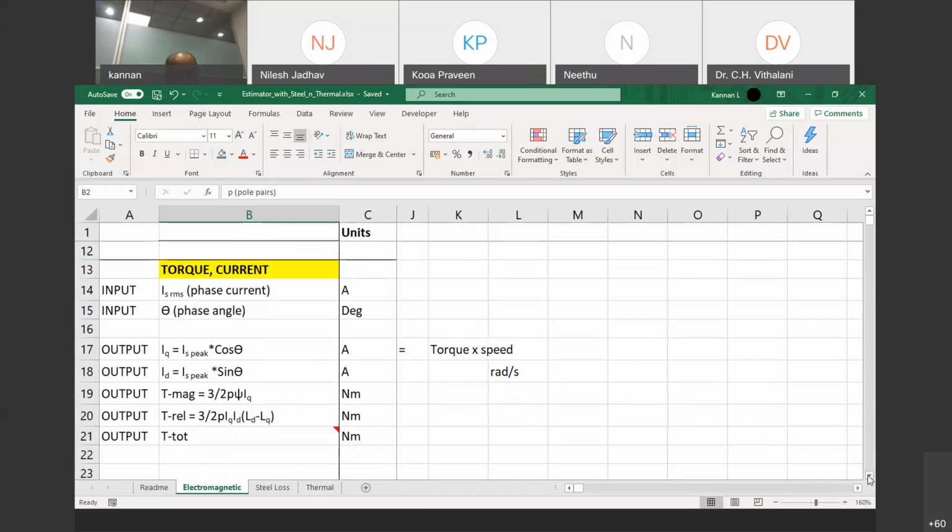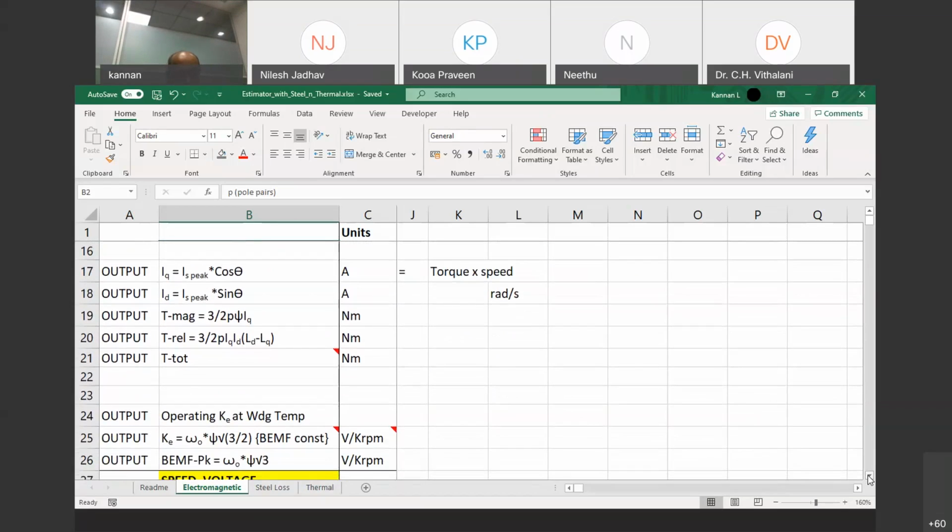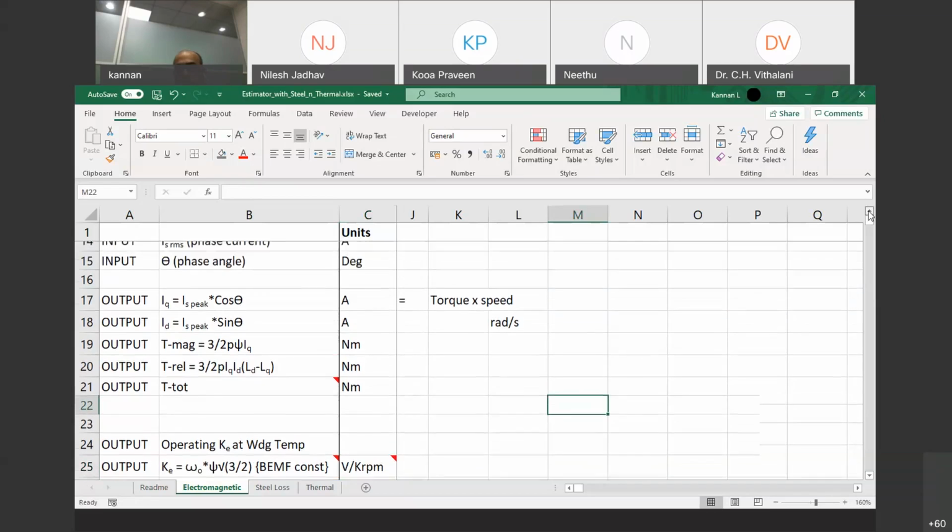You can look at the equation here. Supposing I measured the amplitude at 2000 RPM, then whatever amplitude I got, I will divide it by 2 and say that is the amplitude per 1000 RPM, and that's called the back EMF constant. And if I know the back EMF constant, volts per 1000 RPM, then I can use this formula to back calculate the Xi, which is the magnet strength. So I can find the magnet strength without opening the motor.